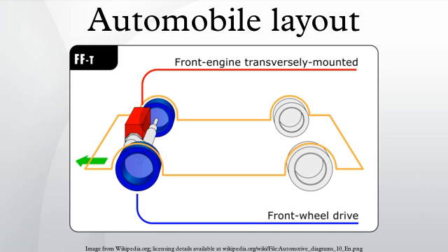Weight shifting limits the acceleration of a front-wheel drive vehicle. During heavy acceleration, weight is shifted to the back, improving traction of the rear wheels at the expense of the front driving wheels. Consequently, most racing cars are rear-wheel drive for acceleration. However, since front-wheel drive cars have the weight of the engine over the driving wheels, the problem only applies in extreme conditions in which case the car understeers.